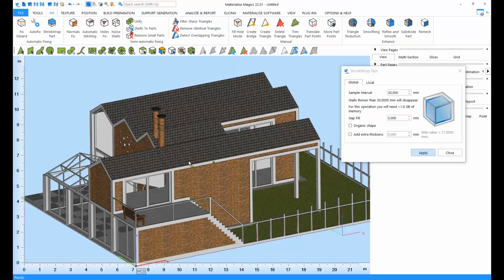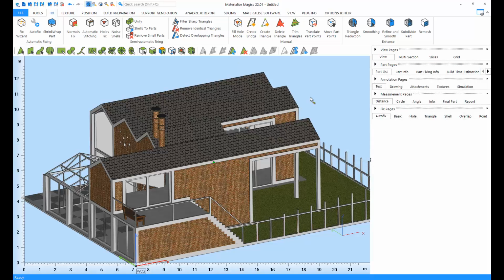A fixed file is ready to be edited and enhanced for printing efficiency and part performance, depending on the 3D printing technology you're using. For example, you can hollow your parts or add honeycomb structures to make them lighter, or cut large parts into smaller pieces if they're too big for your machine. You can even label your parts. If you'd like to learn more about editing and enhancing, please see our tutorial on editing files.